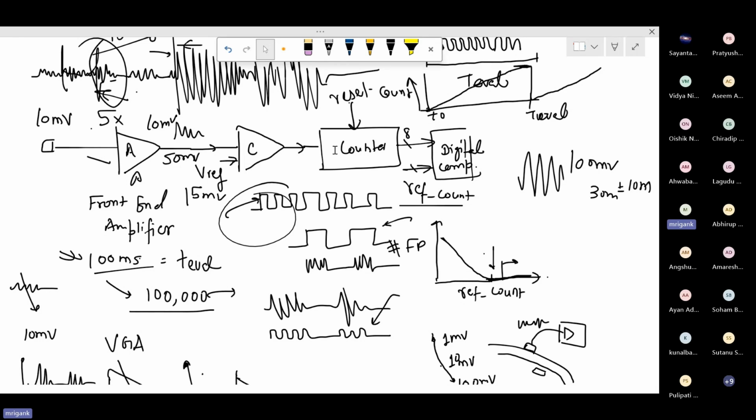You can instantiate those, because the counter design will not be very sensitive here, as we are not designing a very high-speed counter. Even the counter itself is available, I think, in LTspice. So for these two modules, the counter and the digital comparator, it's okay to take them directly from LTspice. You don't need to go to transistor level. But in the real chip, you need to be aware of how you will design the counter, for example a ripple counter. We already saw that lecture on how to design a ripple counter. Likewise, the digital comparator: you have seen digital logic design, and I have explained the sizing of NAND gates, NOR gates, fan-out, loading effect, all those things.